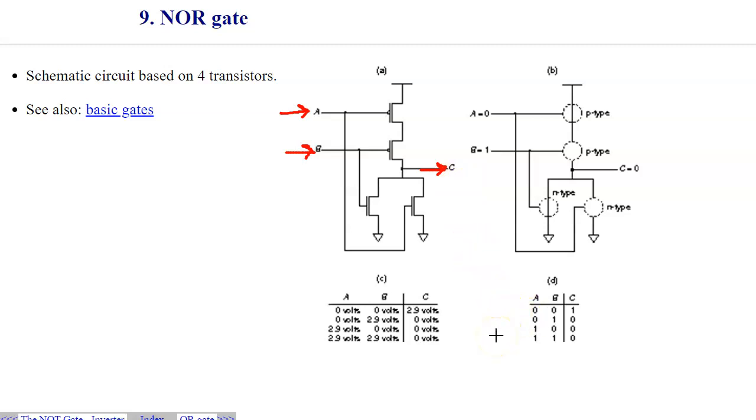And if you recall, an OR gate, or OR logical function, would take two inputs and convert them to an output using the logic that only when both signals are 0, then the output is 0. In all other cases, the output is 1. In a NOR gate, the situation is reversed. Only when both inputs are set to 0, the output is 1. So basically, this is an inversion of an OR logical function.